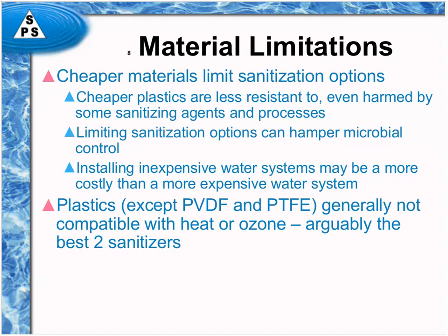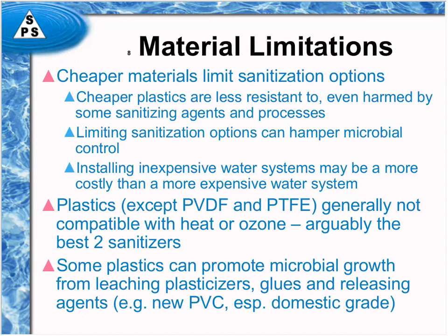Some plastics, such as PVDF and PTFE, which is Teflon, generally are compatible with heat and ozone, but other plastics like PVC and polypropylene and some of the other plastics that are sometimes used are not compatible with heat and ozone. And the unfortunate thing is heat and ozone are probably the two best sanitants you could use.